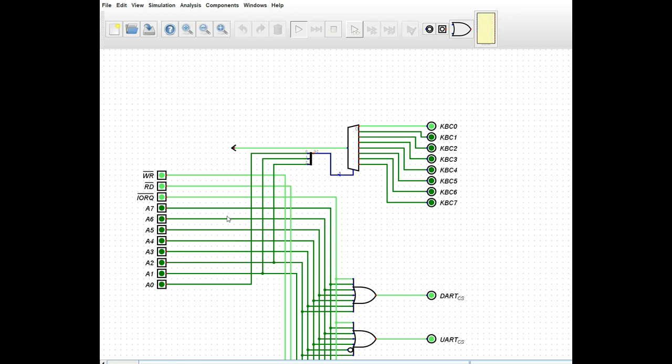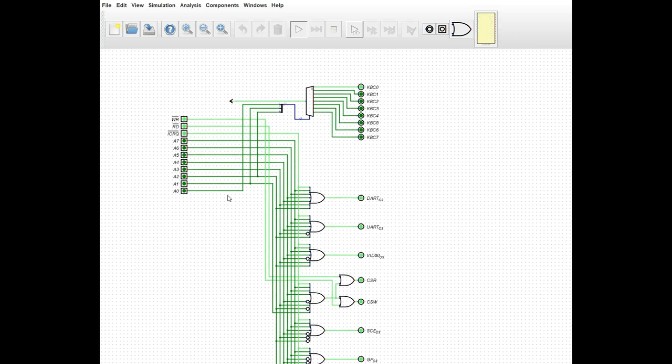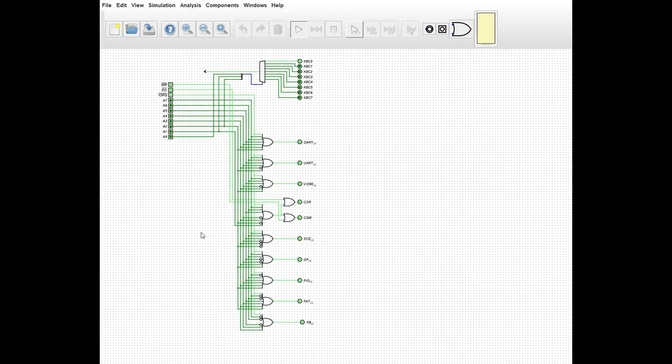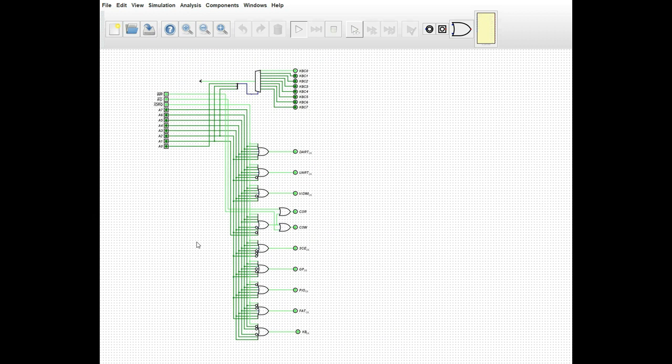So we're actually already booted up in simulation now. As you can see, column 0 is lit up, and the reason for that is because all 3 of those pins are low. If we raise 1, we get column 1. Second one, we get 2, we get 3, 4, and so on up the line. So with that, that actually completes our decoder.